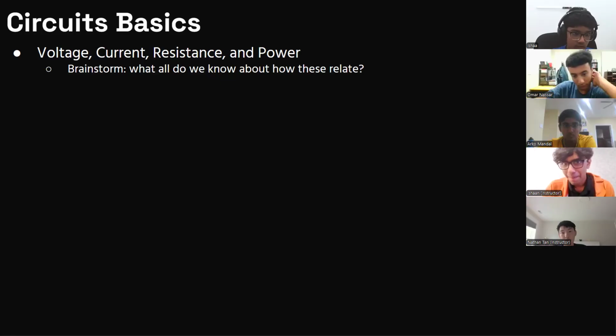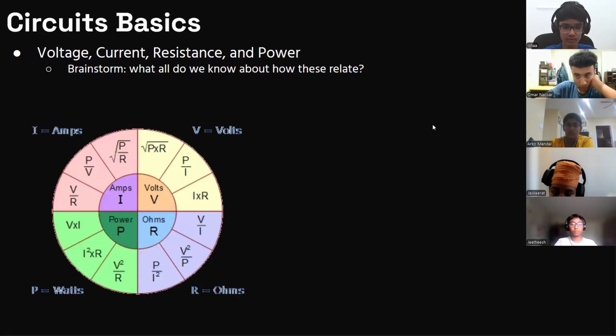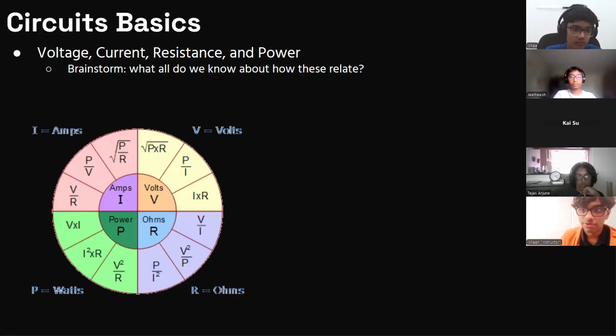First of all, there's Ohm's law, which is V equals IR. But then there's also power, which is V times I equals P. If we combine those two, then we get the other relationships, like V squared over R is power, and I squared times R is power. Yes, point number one: all these important relationships are great for getting you power, current, and voltage.